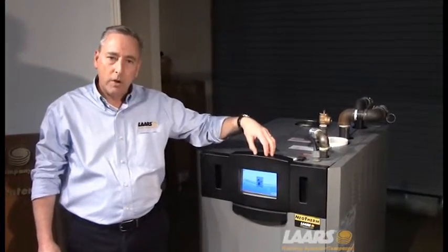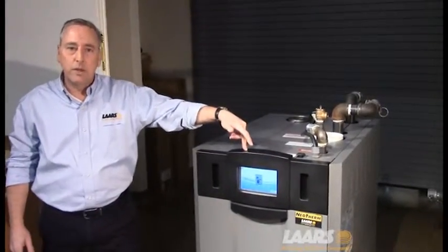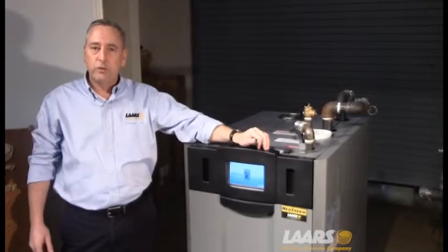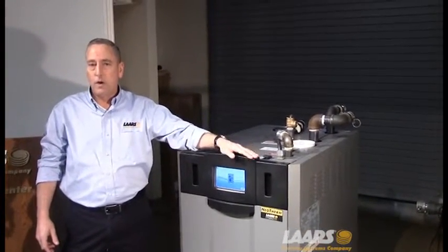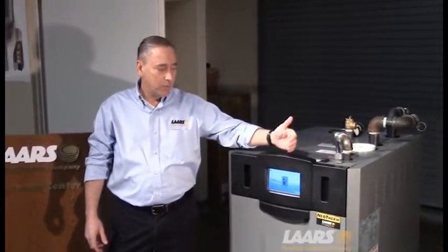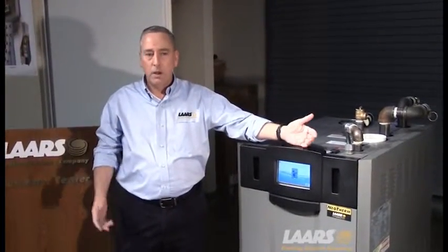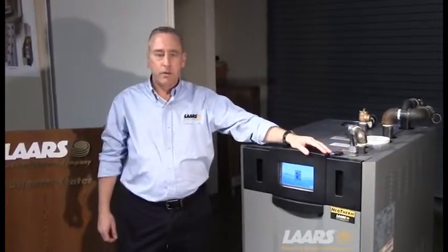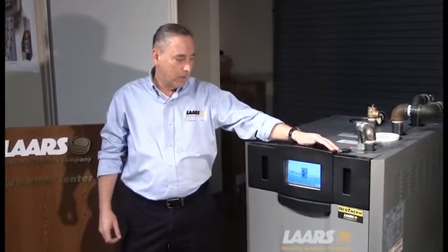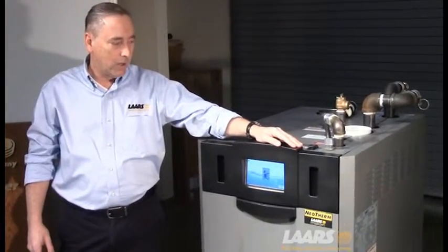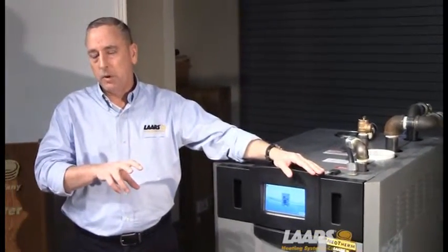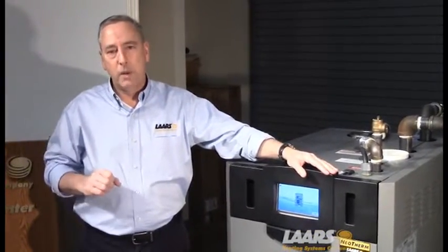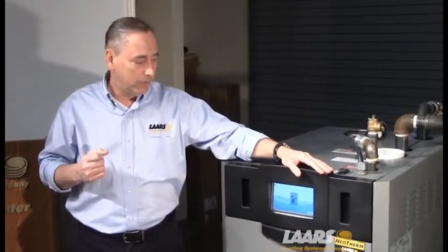The lead boiler always has the system sensor landed on it, and if you're utilizing outdoor sensing or outdoor reset, you want to land that outdoor sensor on the lead boiler as well. The lead boiler would lead lag rotate based on runtime and things of that nature. So what we're going to do here is set up a couple of tabletop units. We'll go through the programming, setting up the lead boiler, and then simulating setting up the lag or slave controls.